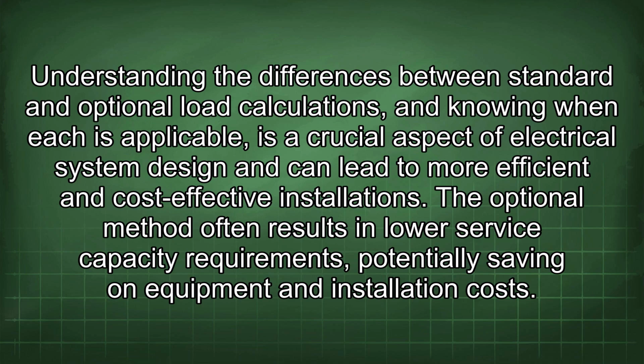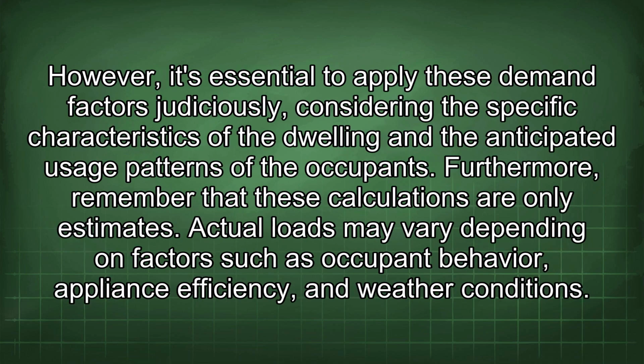The optional method often results in lower service capacity requirements, potentially saving on equipment and installation costs. However, it's essential to apply these demand factors judiciously, considering the specific characteristics of the dwelling and the anticipated usage patterns of the occupant. Furthermore, remember that these calculations are only estimates. Actual loads may vary depending on factors such as occupant behavior, appliance efficiency, and weather conditions.